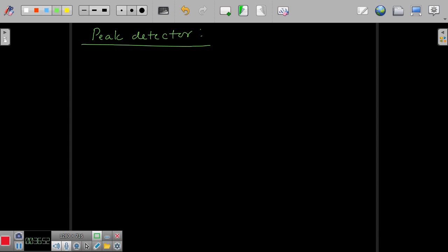So let us say that the temperature is continuously being monitored in a day, for 24 hours. The temperature is an analog quantity. You have a temperature sensor, and you get the temperature output in the form of a voltage level or something like that. So if you want to know the maximum temperature measured in a particular day, that is where you can make use of the peak detector.